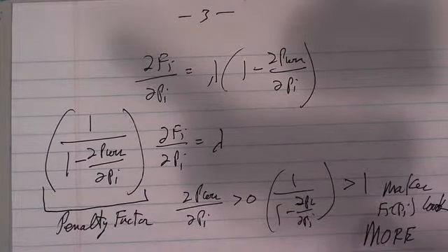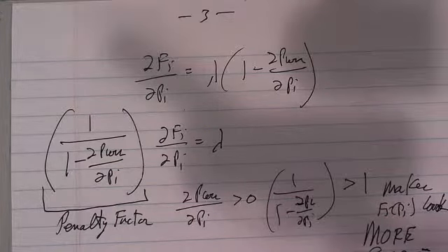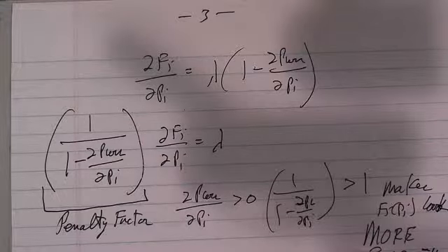It makes it look more expensive because it multiplies in the same way that a fuel cost would. So it's like saying, okay, here's your fuel cost, and I'm going to multiply it by a number that's 1.02. It's 2% larger. The cost of fuel on that generator just went up by 2%, and that is going to make the generator operate at a lower amount compared to all the others because it's making it look more expensive.